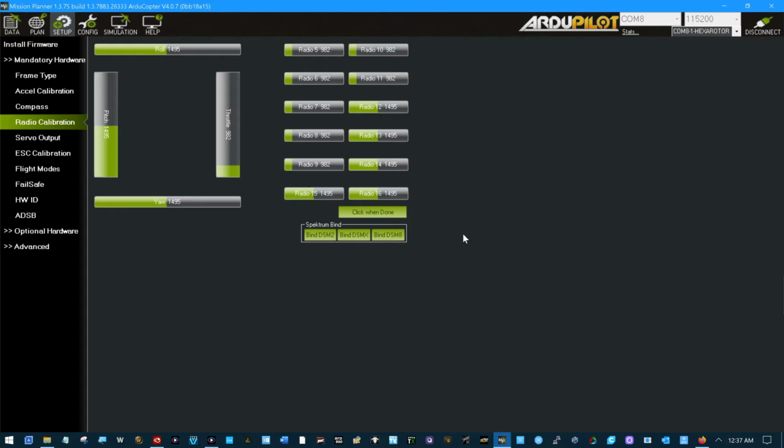the flight controller getting their calibration. You can see I just raised the throttle. You can see right here I've got a pulse width of 2005 here at a high throttle. Now I'm going to lower the throttle and it's 982 at the bottom. That's a little different than that servo tester I had on the bench, isn't it? Yes, it is.